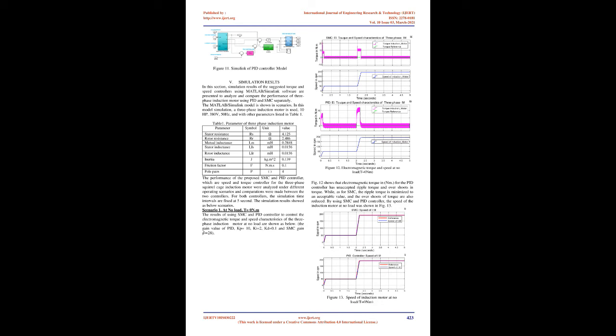The steady-state error can be reduced by using the proportional controller, P. But the proportional controller will not eradicate the error. Therefore, the integral controller can be used to minimize the error close to zero value and increase the stability of the system. But the disadvantage of using the integral controller is that it will effectively increase the response time. To anticipate the future behavior of the error signal, the derivative control can be used to correct actions based on the rate of change in the error signal. Thus, it minimizes the error, increases the stability, and improves the transient response of the system.